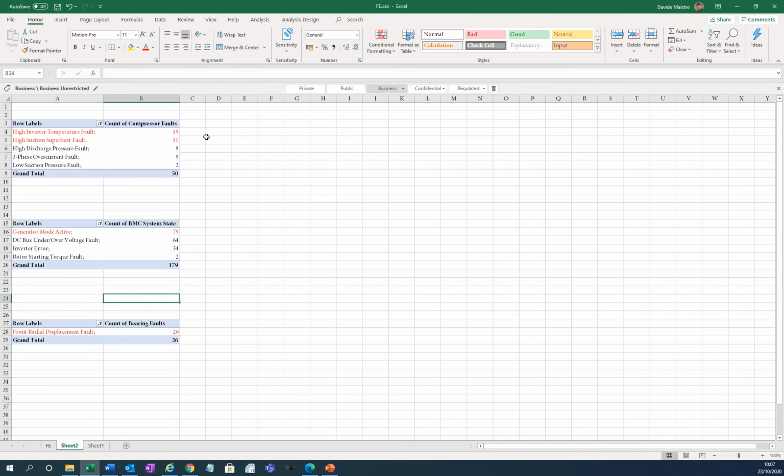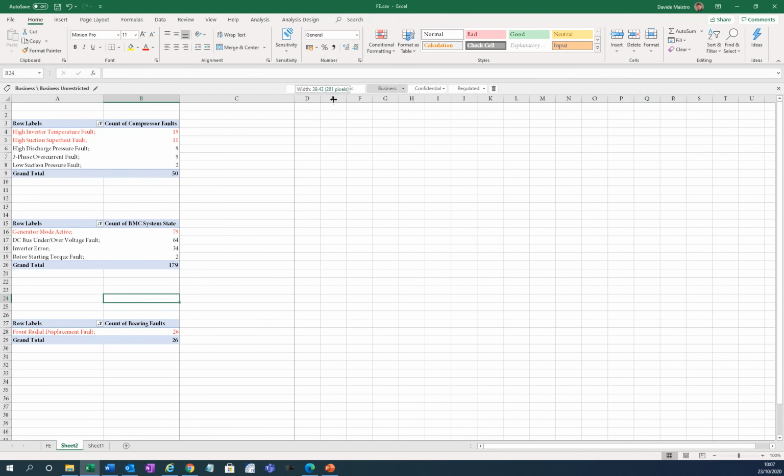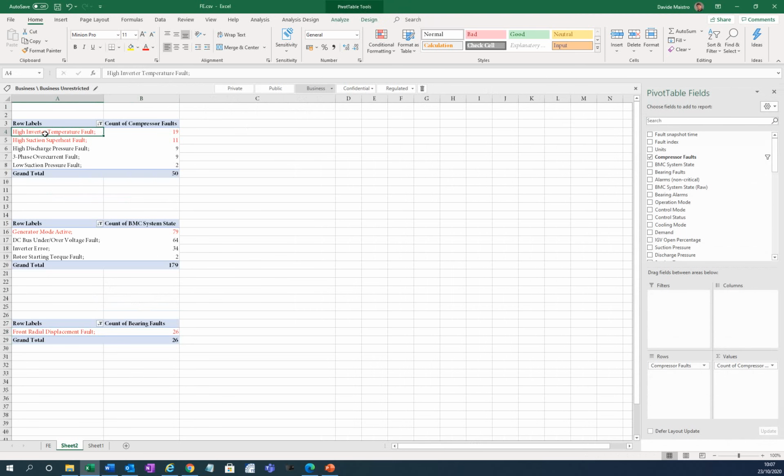Okay. Now at the beginning I recommend you to go through all these faults, or whatever fault you find in your fault log, by looking at the service manual. Okay, so the service manual will tell you a lot about what to look at on the compressor and outside of the compressor at the system level.